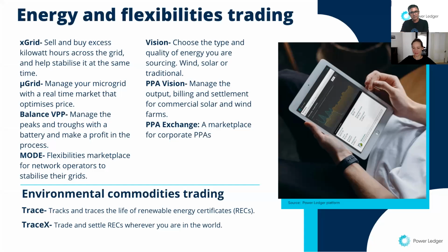And these could also come from microgrids as well. So for example, there could be a community level microgrid residential battery, which is what we actually have in Fremantle, in one of our project locations in East Village. And batteries like these can also participate and be aggregated along with other distributed batteries to act as a single large virtual battery and offer solutions to the grid or even the wholesale electricity market for energy arbitrage opportunities.